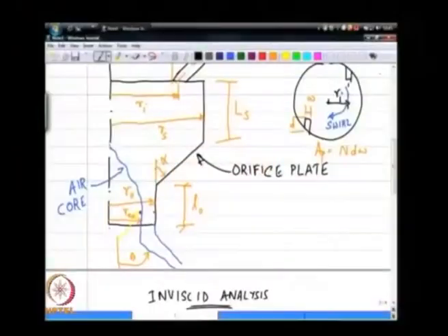because I can apply Bernoulli's equation on two points on a given streamline, and if all the streamlines are originating from the same stagnation pressure delta P, I can essentially apply Bernoulli's equation even across two streamlines at two different points, because they are all amounting to the same stagnation pressure. We will take advantage of this later on.